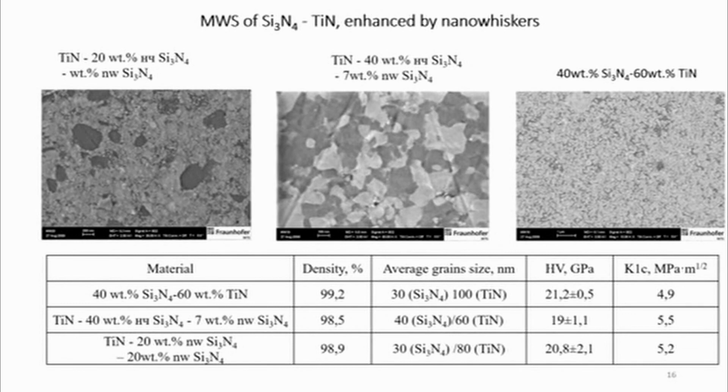This is another significant advantage compared with spark plasma sintering. This point is essential in order to use this sintering technology, where the final dimension of a sintered component has to be almost constant in order to reduce the final machining cost of the nanocomposite. Here you can see how it can be sintered to a near fully dense density.